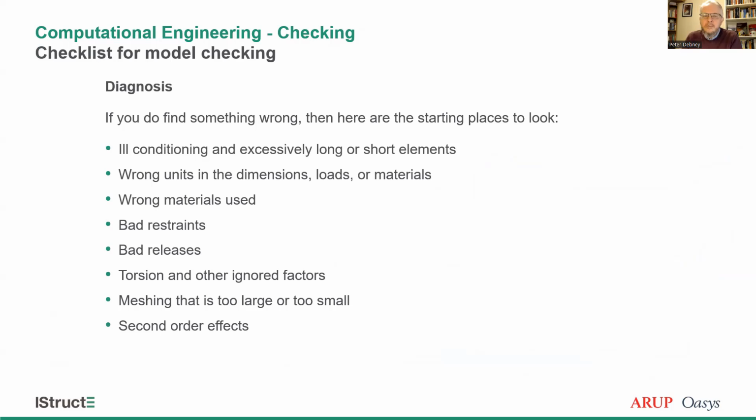Classic one, a few years ago, my colleague was doing a vibration analysis on a shopping center in Doncaster. And the natural frequencies came out considerably lower than we were expecting. It turns out he had modeled a 150 mil steel floor rather than a concrete floor. And not surprisingly, it was lots different, heavier than we expected. But we knew what to expect, and therefore we spotted the error, had a laugh, and corrected the model.